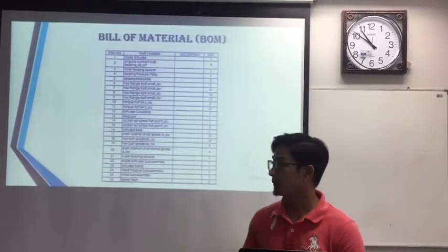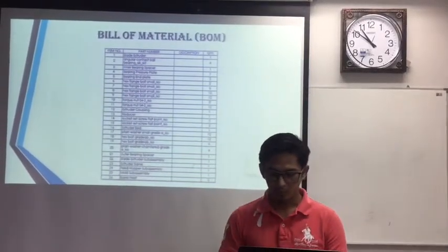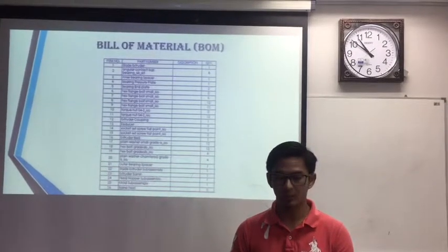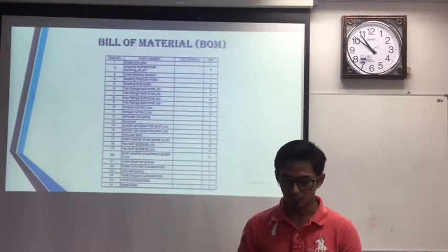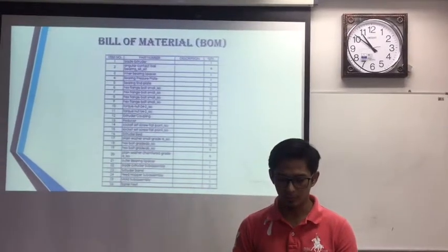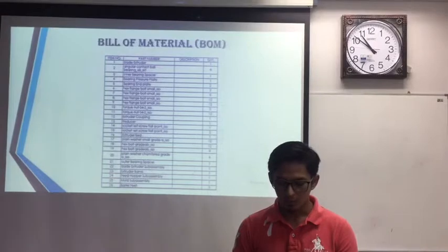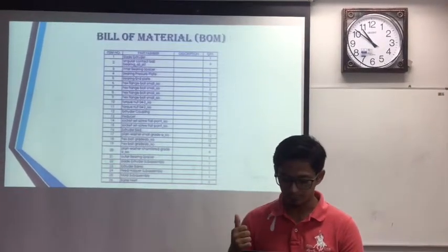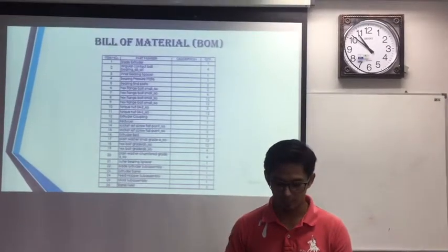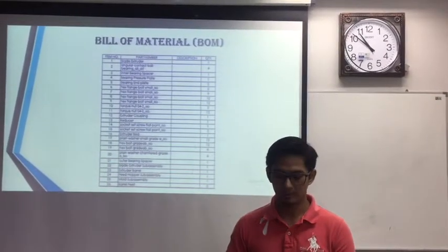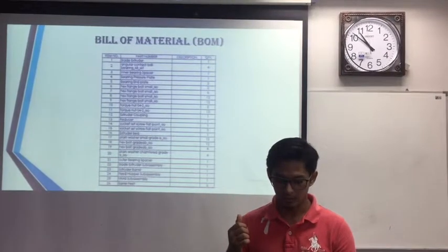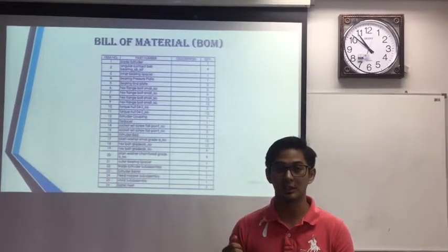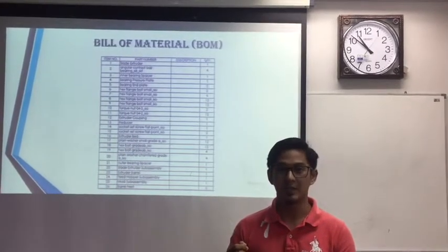I will continue about the bill of materials. There are 26 parts in this machine. This drawing is generated from SolidWorks to get the quantity of parts used in this machine. The higher quantities are from the bolt, nut and washer, with a quantity of 12. The reducer part is the motor for the machine that has a spur gear to control the main part of this machine, which is the blade extruder.